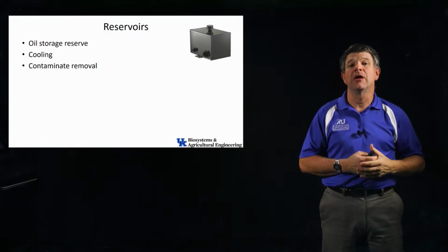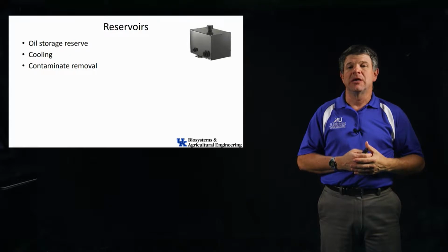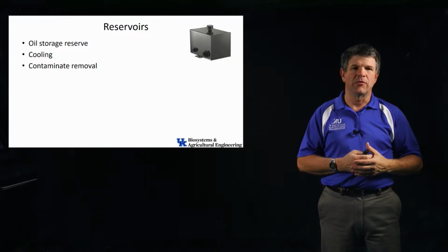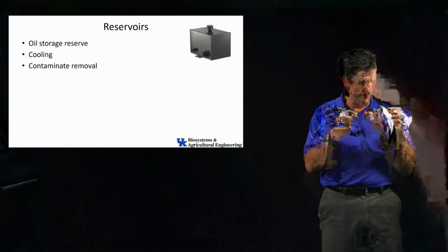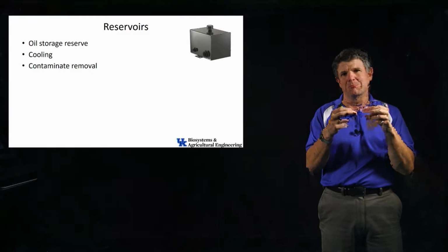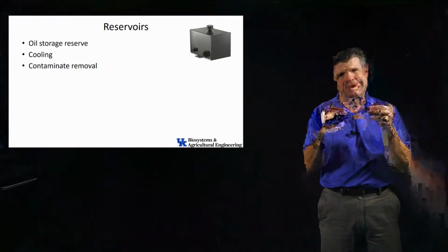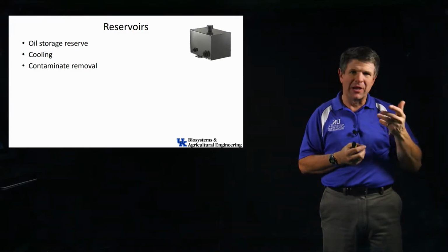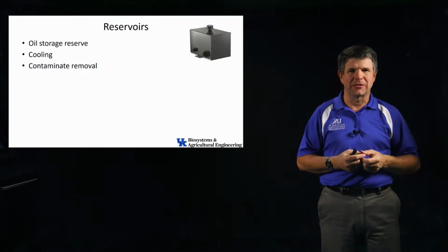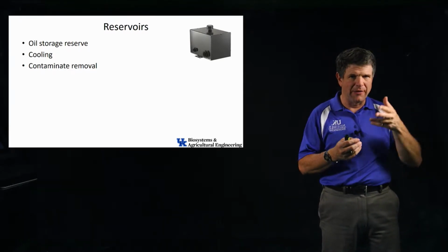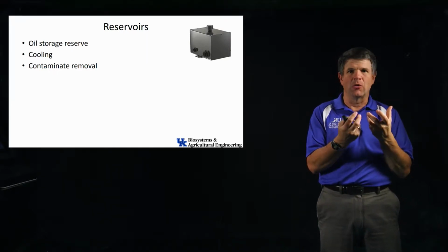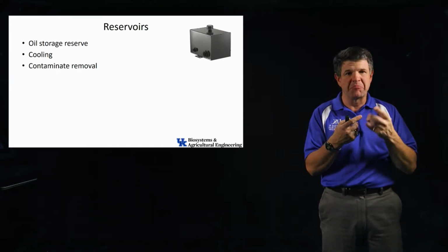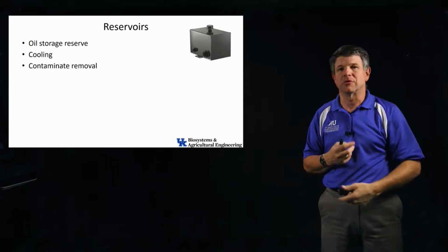The other thing that we look at with the reservoirs is contamination removal. So through the system, we have valves and there's no seals or anything. It's all very tight tolerance. As things move, we're going to get some wear. We may pick up dirt in the system from other places. So for instance, in agriculture, we have those remotes on the back of a tractor that we can plug hoses into. And if we don't clean the hoses off before we plug them in, all the dirt that was on the end of the hoses goes right into the system.